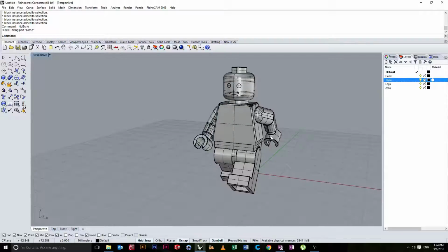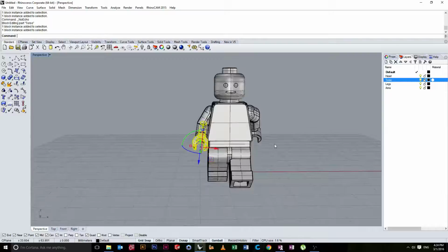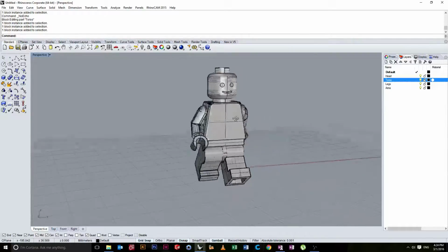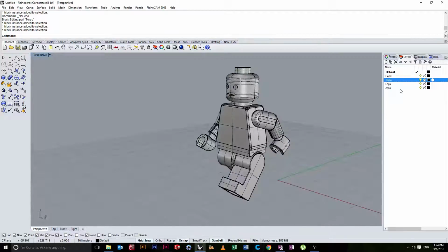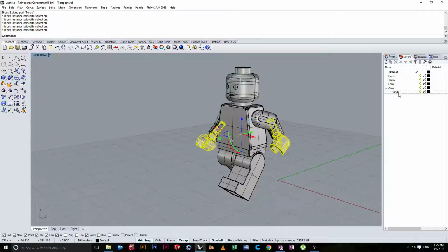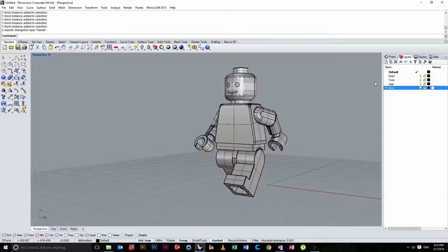Now what we haven't got on a layer are the hands, or this little joint through here. And I'm going to put those on what's known as sublayers. So that's a layer within a layer. I'm going to put the hands on the sublayer of the arms. To do that, I'm just going to select the arms layer and click New Sublayer just here. I'll call it Hands. Okay. I'll shift click, right click and change object layer. Okay. And now you'll notice I can minimize that layer, turn it on and off as one, or I can expand that layer and just turn the hands off individually.